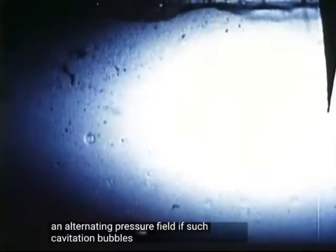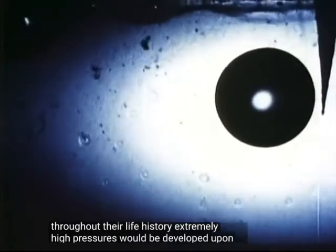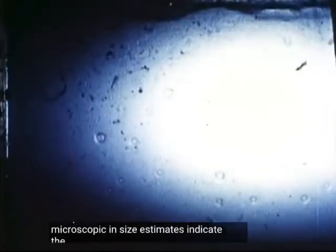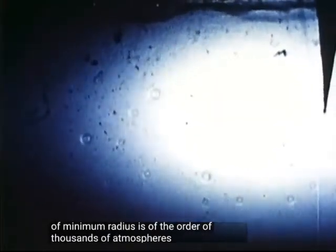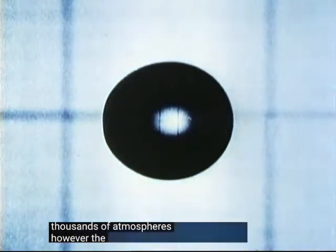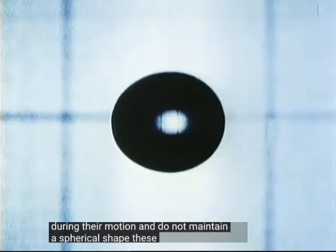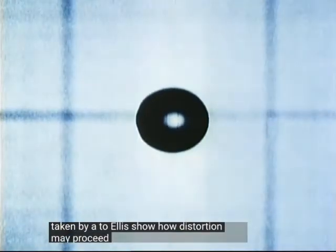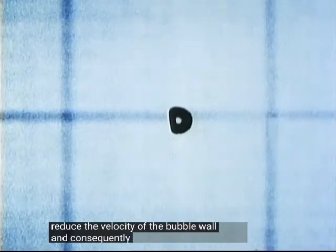If such cavitation bubbles remain spherical throughout their life history, extremely high pressures would be developed upon collapse when the bubble is almost microscopic in size. Estimates indicate the pressure produced near the position of minimum radius is of the order of thousands of atmospheres. However, the bubbles become unstable during their motion and do not maintain a spherical shape. These photographs, taken by A.T. Ellis, show how distortion may proceed. Such deformations tend to reduce the velocity of the bubble wall and consequently the pressures that are developed.